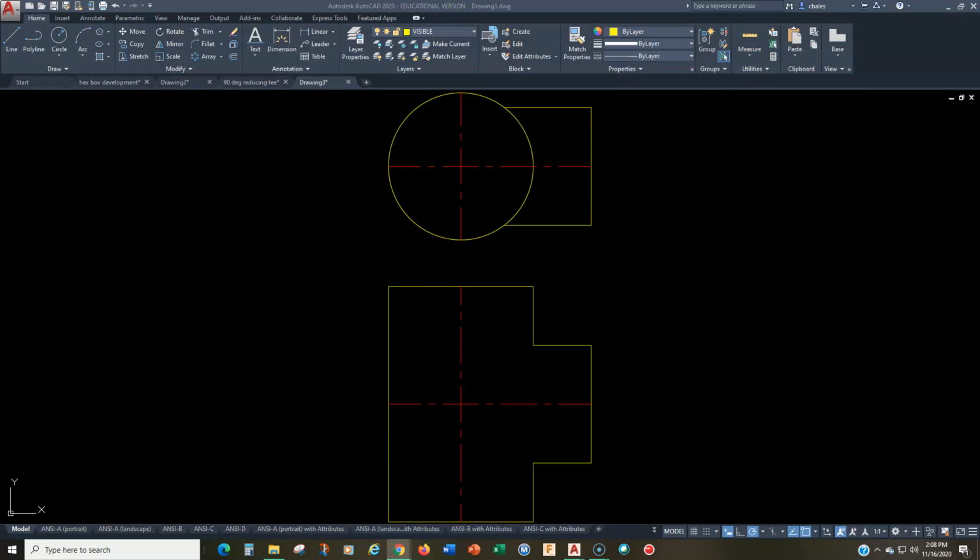So what am I talking about when I talk about a line of intersection? Well, here are the two parts. We have the vertical tube, right, and the horizontal tube, right? This is the top view, front view. There's no right side view given. That's something that you'll have to construct. But when we talk about a line of intersection, what we're talking about is the line that exists when we have the horizontal tube intersecting with the vertical tube right here. So there'll be a line where these two go together, and you can see that that part is missing in the drawing in the book, and that's what you have to construct.